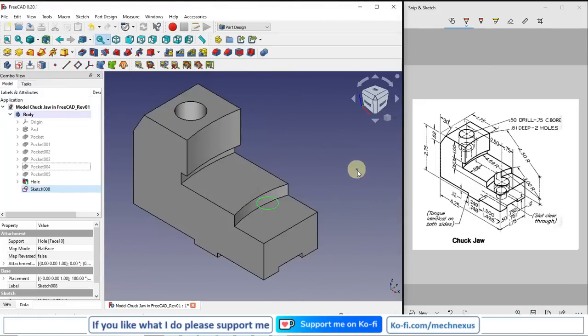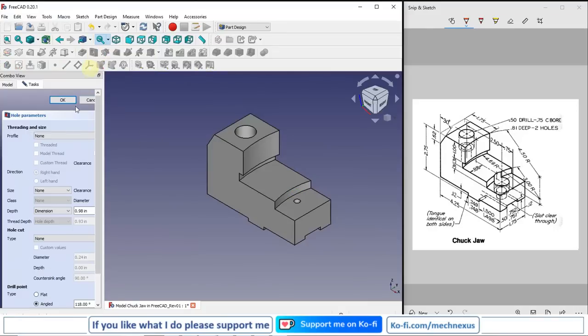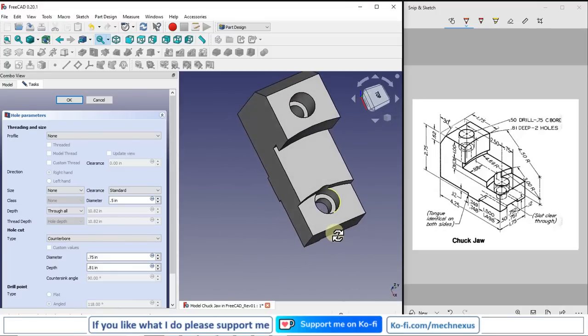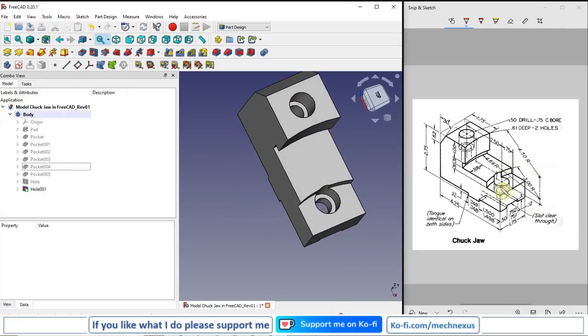Now we will say close, and now we will go for the hole features, and we will do the same thing which we had done for the previous hole. So here diameter through all is 0.5 inch, and it is through all. And now here we will go for the counter bore, and here it is diameter 0.75 with a depth of 0.81. So as you can see, we are seeing the same like as hidden here, our holes.